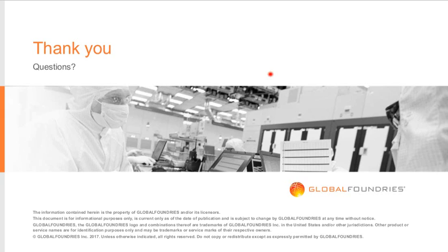The high-Q MIM cap has lower density but much higher Q factor, so it can be used in the signal path, in the millimeter wave signal path. Low density is also good for the millimeter wave design because the capacitor will be small, so the low capacitor density will show lower process variation, and the high Q can improve the signal path loss.